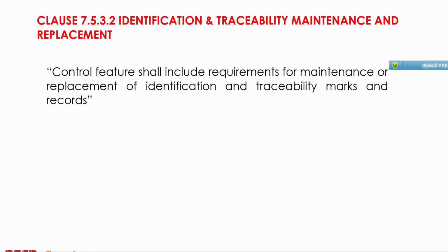Again, this technical standard is more explicit than 9001, whereby replacement parts need to be traceable and also control features identified. And in one company I worked with, there was a process called 3.1C relating to castings, where the certification body, in this case Lloyd's inspectors, were responsible for the transfer of markings onto the fitments from the original castings, because the original markings had been machined out.